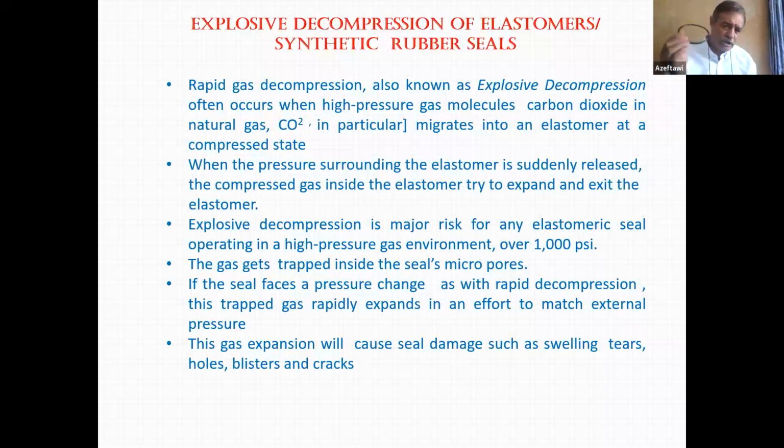Do you change only the 2 rubber elements? No, you change all, because they are all exposed to the same condition, the same environment. If you change only 2 and put it back into work, after half an hour another one will have this phenomenon. Another one. So please change them all. They are all damaged already.